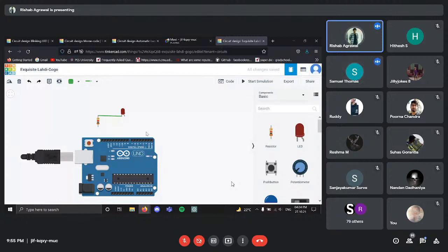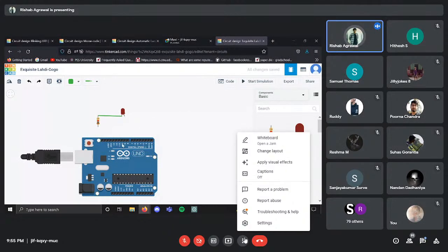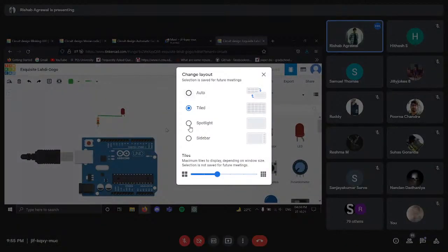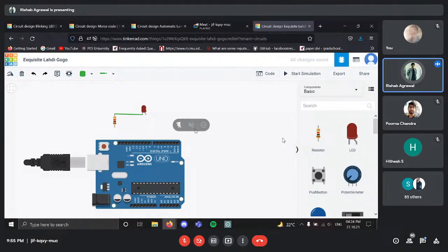Okay, so that's pretty much it. Also, instead of connecting a resistor, is it not possible to control the current flow so that it doesn't overload the LED? Actually, I think the voltage that an Arduino Uno provides on these digital pins is fixed. So you will have to use a resistor, because if the voltage is fixed, the only way you can control the current is using the resistor. There could be a way, but in the implementations and projects I've worked on so far, I have never seen changing the amount of voltage that these digital pins get. Got it. Thank you.